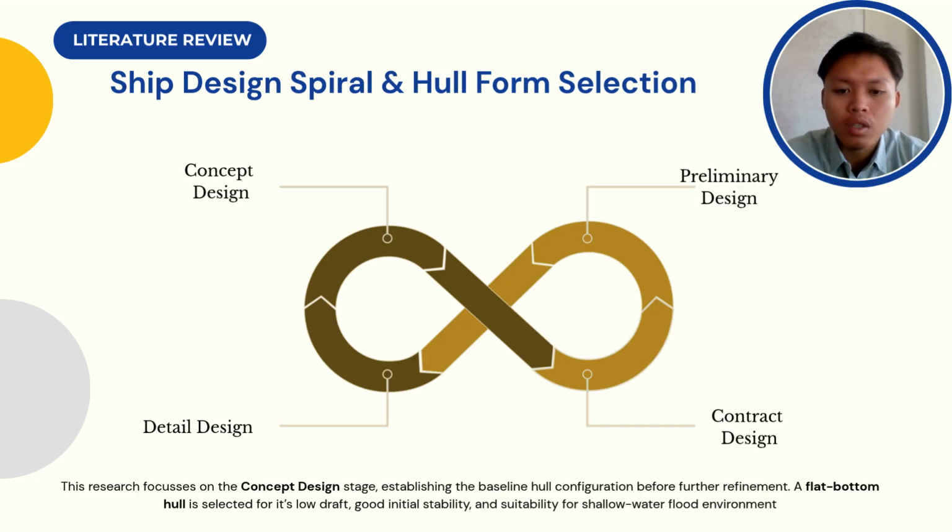This research focuses on the concept design stage because it forms the foundation of the entire vessel design process. Regarding hull form selection, a flat bottom hull is chosen for this study. The main reason is that a flat bottom hull provides a shallow draft, which allows the boat to operate in shallow flood water. It also offers high initial stability, which is important during rescue operations when passengers are boarding or moving around the vessel. This characteristic makes the flat bottom hull highly suitable for flood relief applications.